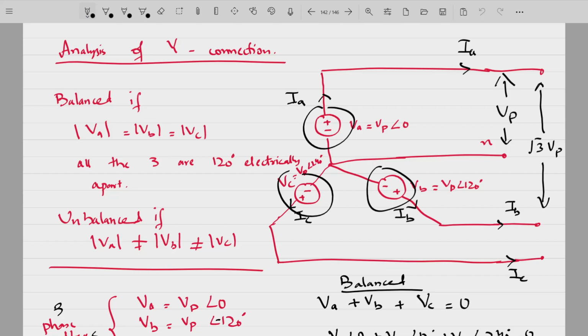So there may be cases where you actually have access to a three-phase system and you want more voltage across two different phases, so you can tap into two different phases and have more voltage available to you. Another case is illegally hooking extra or tapping into two different phases, that is something different. But in either case, you can obtain more voltage by tapping into two phases rather than tapping into a phase and a neutral.